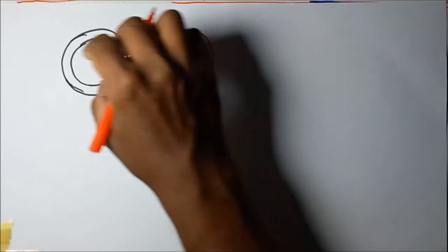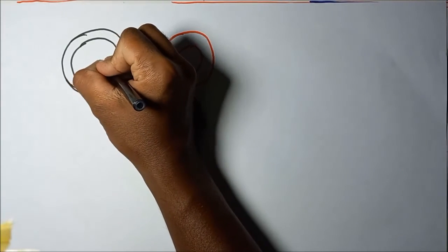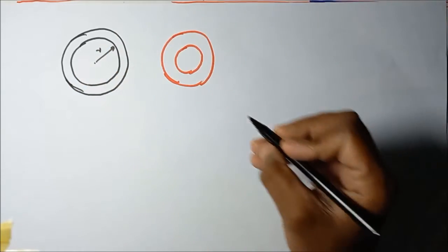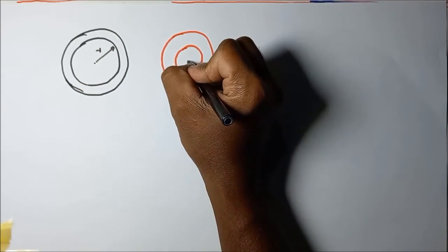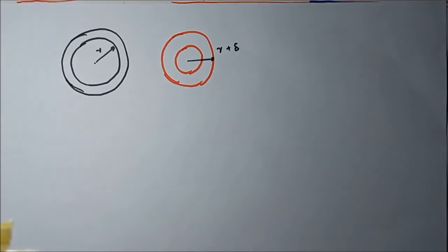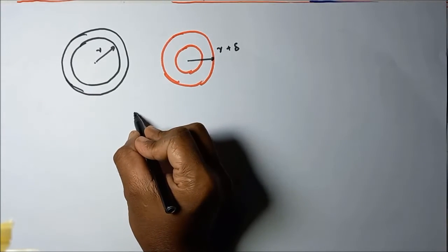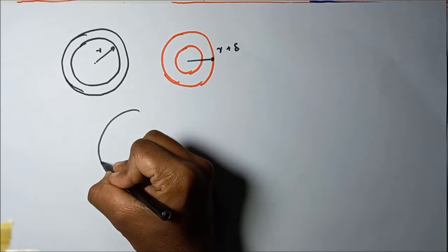This is the cylinder we are going to insert in this cylinder bore. Let's take this radius as r. Then this radius is equal to r plus delta. The delta is the shrink fitting tolerance. Then, after assembling these two cylinders, it will come to this kind of shape.